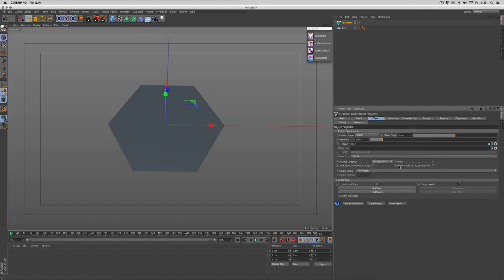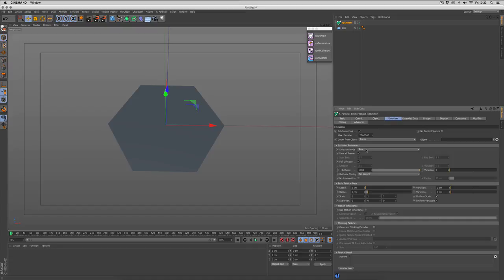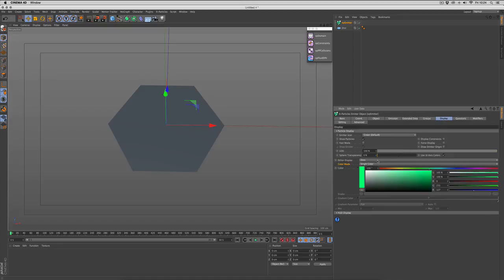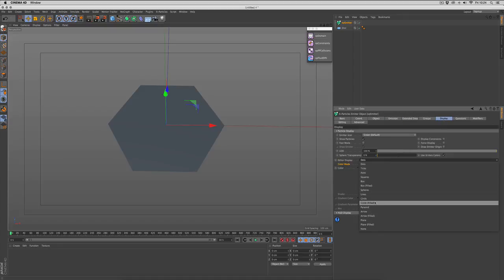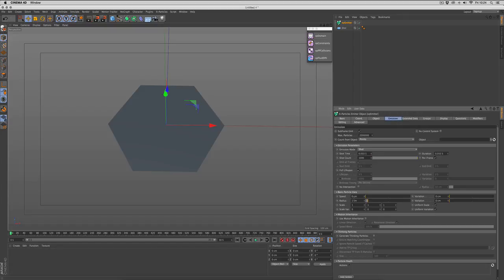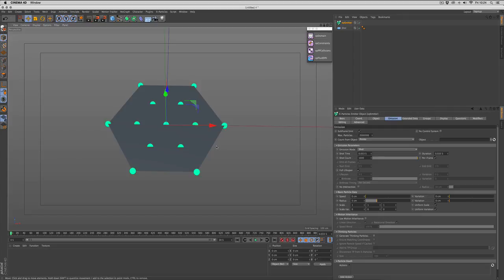We also need to enable one particle per source element and make sure it's in shot mode so it only emits for one frame. I'm going to change our display from dots to circles filled and our size to 5. So now if I go up one frame, we'll get our particles emitted on these points. We can hide the disk.